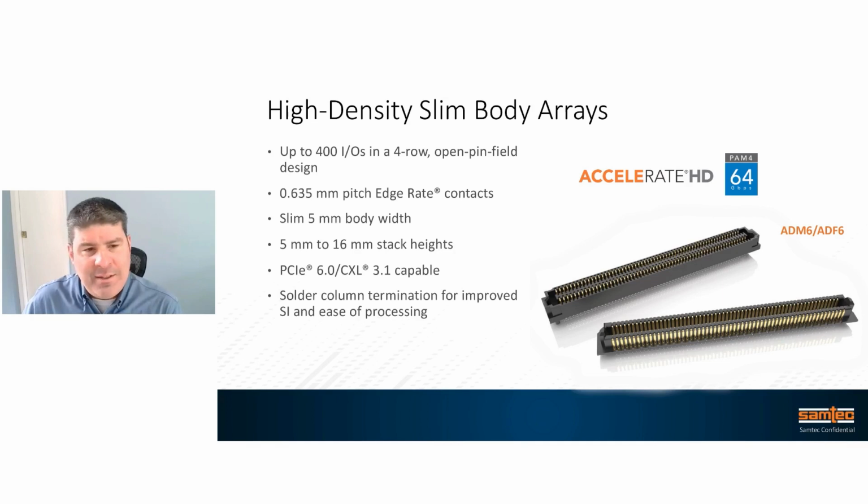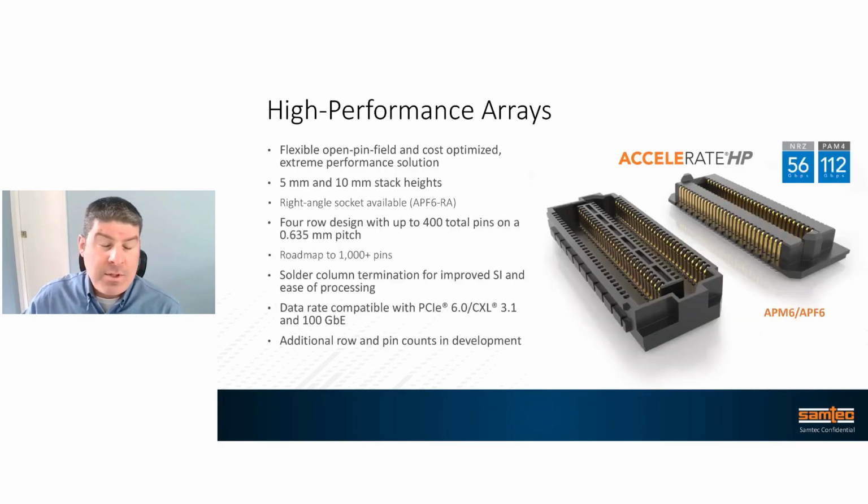Our Accelerate HD solution is a 0.635 millimeter pitch edge rate contact. It's a 5 millimeter body width, various stack heights. The reason that we mention it here is because Accelerate HD is very popular on a number of AI system on module platforms on the market. It does give you access to PCI 6 data rates at 64 gigasample per second, or 64 gigabit per second.